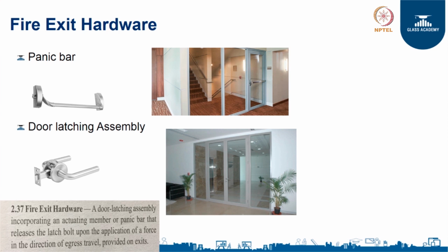So, all fire doors need to be fitted with, if you can see the image in the bottom corner here, a door latching assembly incorporating an actuating member or a panic bar that releases the latch bolt upon the application of force shall be part of a fire exit door. And these doors need to be provided on exits, so that in a state of panic people can get into the passage of evacuation with ease.